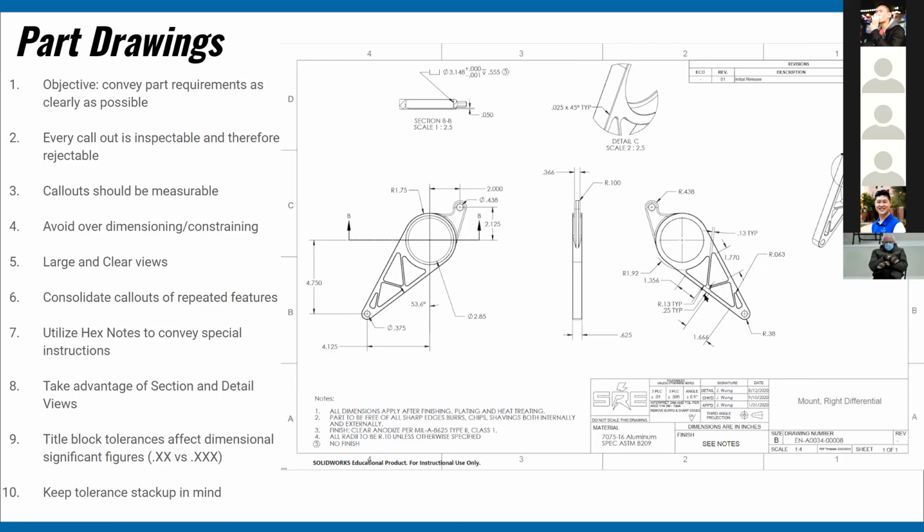Usually it depends on what tier the supplier is in the manufacturing process. In other tiers, they'll bring the anodization to another place to do it, and then you might want to have a separate note on a different drawing and not have it applicable here.